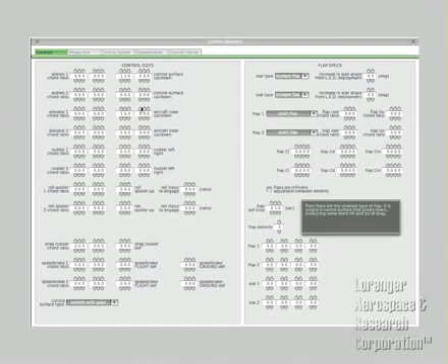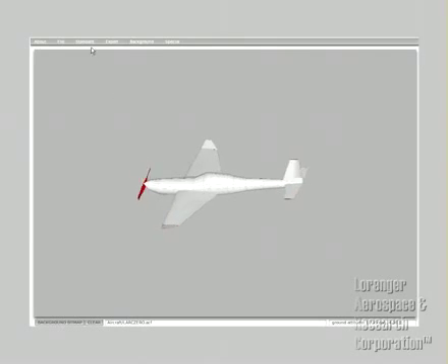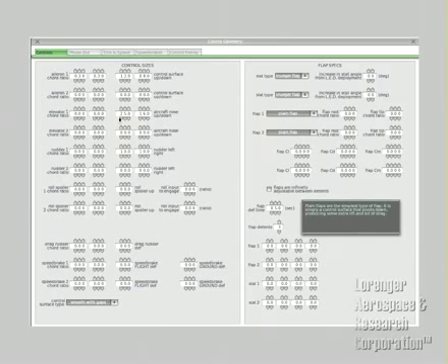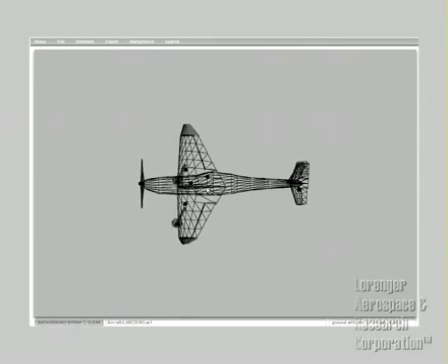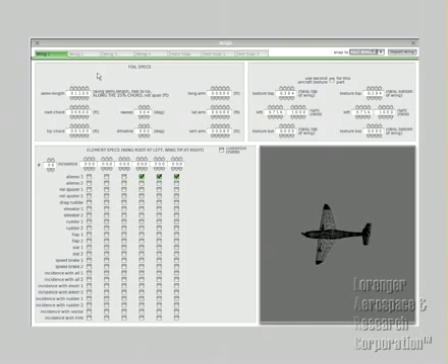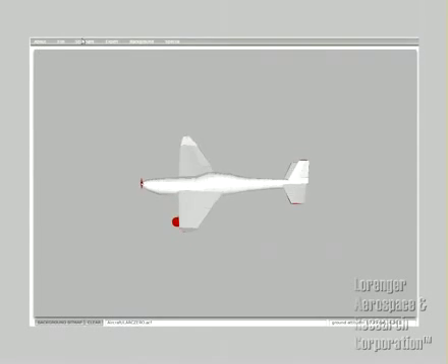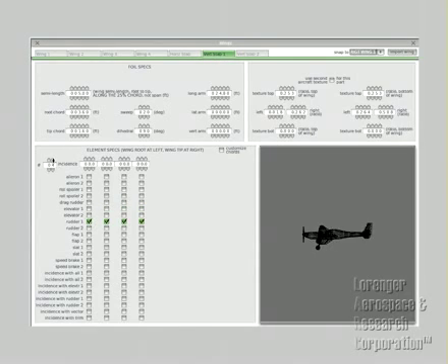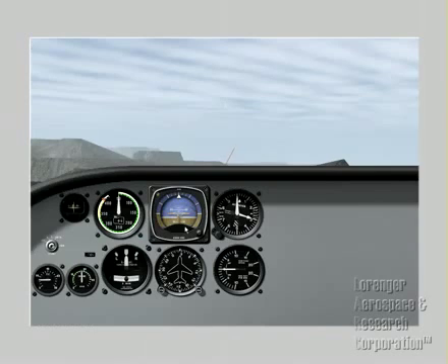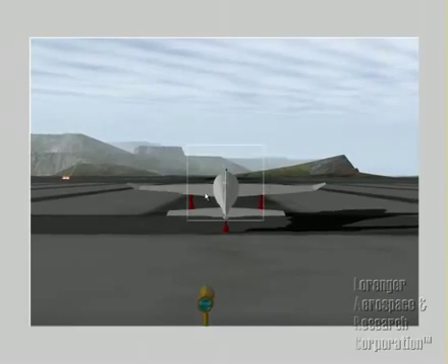Sure are. Here's our control deflections. This is what I was mentioning earlier. Notice you don't see anything. Yeah, there we go. The percentage of the wing hasn't been chosen. And also those ailerons are huge. They're too big. Remember, I'm rushing. I'm doing this on lunch. I'm just flying through it. So here, we quickly test fly it.